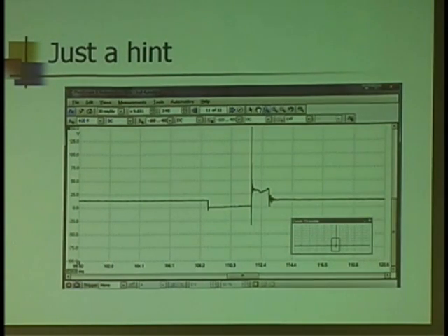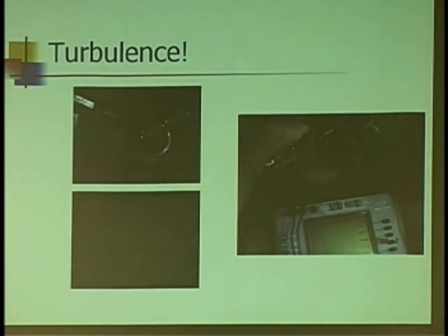Yeah, that's a possibility. And I had a gentleman actually tell me he found the center electrode was actually loose in the body. It was moving up and down as the engine ran. So what happened there? The gap was changing. Okay? The most common, and one you'll see more and more of, is based on turbulence inside the engine. When you have a valve that is not sealing 100%.